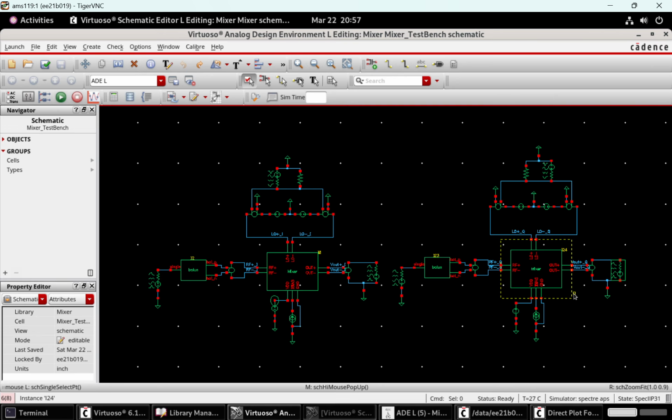So since this is a harmonic circuit, you need to estimate power using HB and not DC. So I hope all the simulation methodologies are clear for the mixer. This is not a trivial simulation setup as in the case of an LNA. So please let me know if you have any questions.